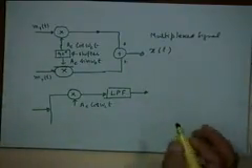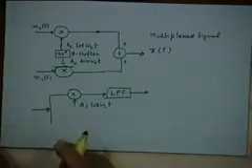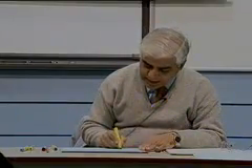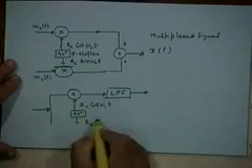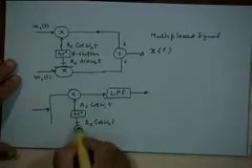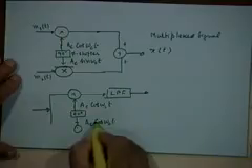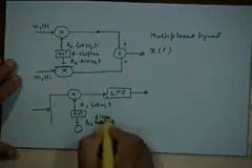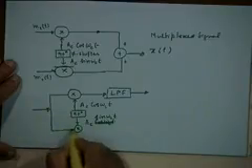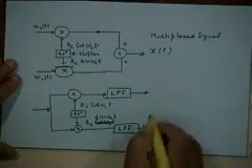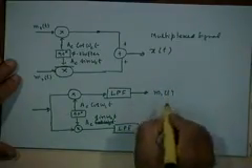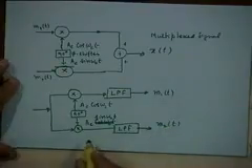The synchronous demodulator is also called a coherent detector, unlike the envelope detector, which is not coherent, which does not require a phase coherence of the carrier and the incoming signal. And similarly, if I use a second demodulator, a second coherent detector, this should be A_c sine omega_c t, followed by a low pass filter. So what will this give? This will give the message waveform m2(t). The first will give m1(t), right?